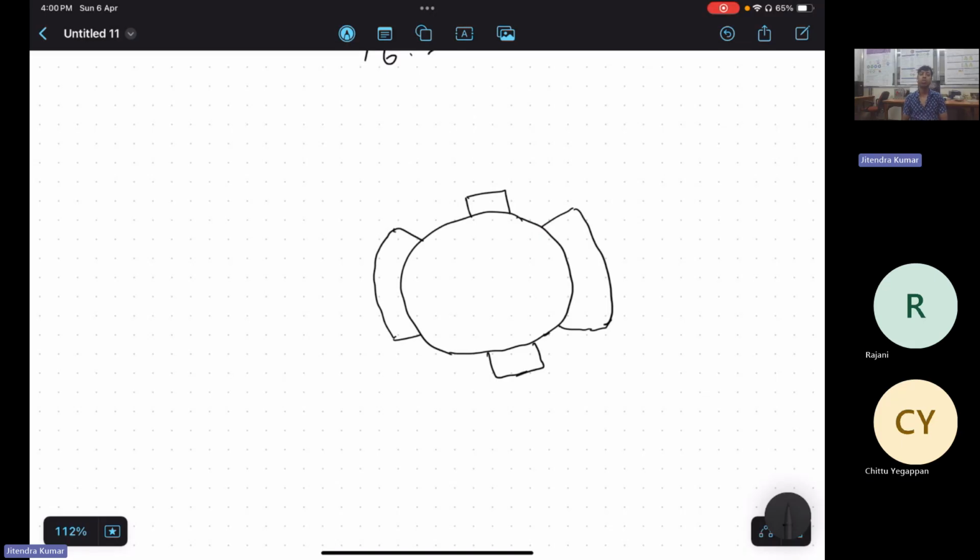So here the symmetric model will not give you accurate values. You must simulate the full model because symmetry is not present in the rotor structure itself, or you may create a difference in the stator. In many research papers you will find that asymmetric structures are used generally to reduce certain harmonics or torque ripple.